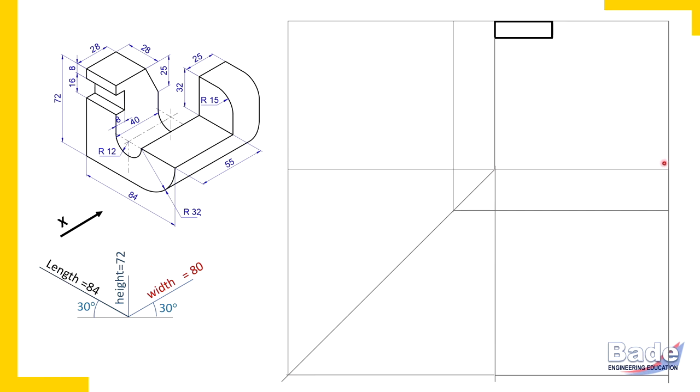Watch here. 32, this is the center line to locate the center, and 32 parallel to height, and draw the center line. So this is how we have located the center. Now with this center, radius 32, complete the quarter circular arc. Now this surface has one more curved edge. It is a semicircular edge. So let's draw this edge.